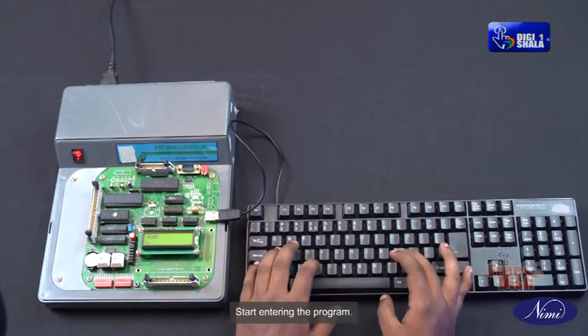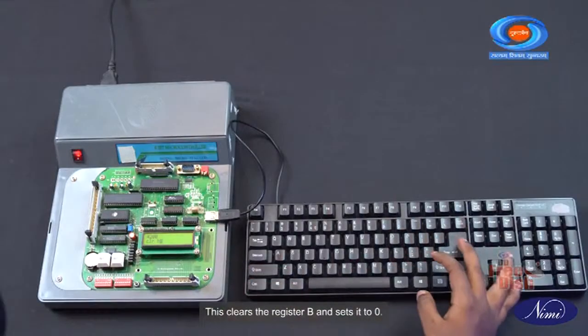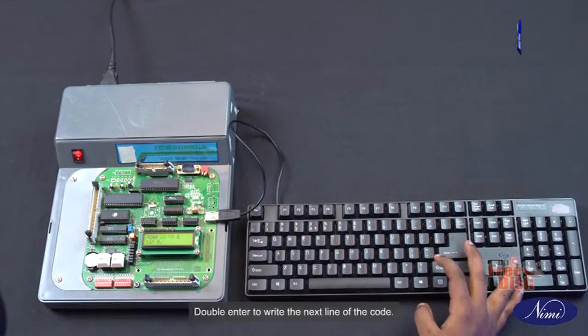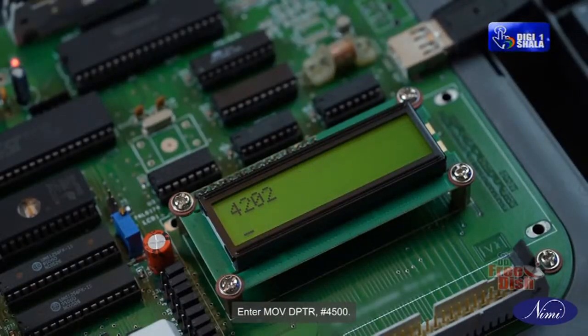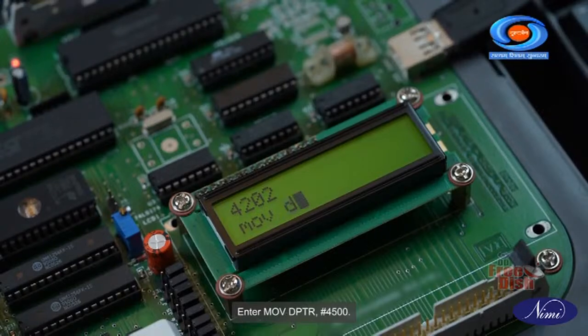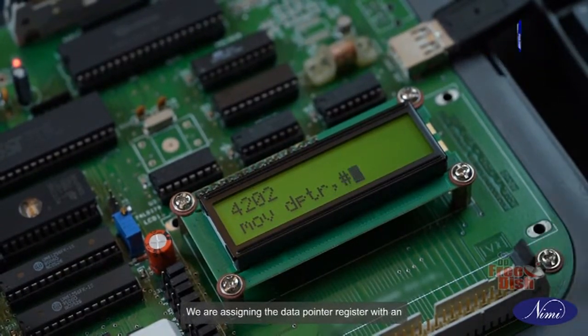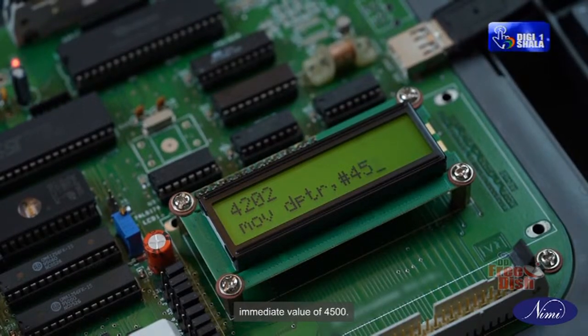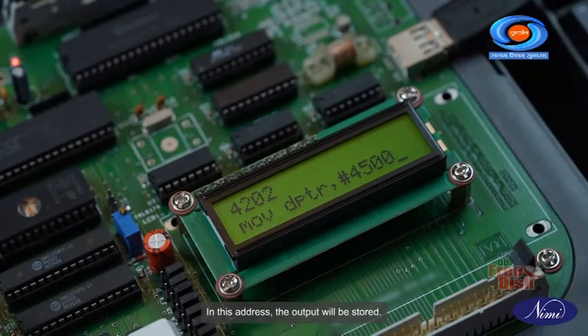Start entering the program. CLR B. This clears the register B and sets it to 0. Double enter to write the next line of the code. Enter MOV DPTR, #4500. We are assigning the data pointer register with an immediate value of 4500. In this address, the output will be stored.